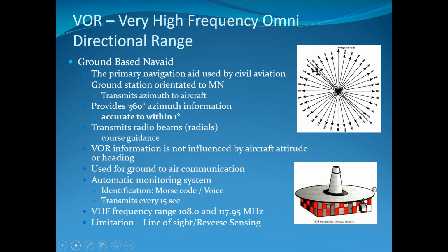So those runways are numbered based on magnetic north, though. So runways are always magnetically aligned. But if you were to go read the METAR for St. George, and the wind report in the METAR was to say wind 190-15 gusting to 20, the METAR is going to be in true. So why it is like this, I don't know. That's every airport. If you read it, it's in true. If you hear it, it's magnetic.